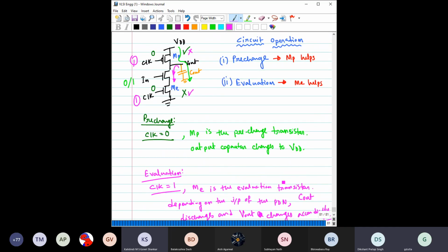So have you understood what I'm trying to say? Depending on the input here. Okay, suppose now here we have made 1 and 1, so this transistor is off, so it cannot charge any further. But this is on. However, if this is only on and here you have given 0, so this transistor is off. So still this V out should retain as VDD only, at VDD level only, right? However, if you make it 1, then it should discharge and it should fall to 0, right?